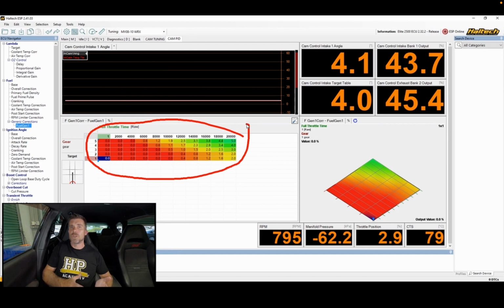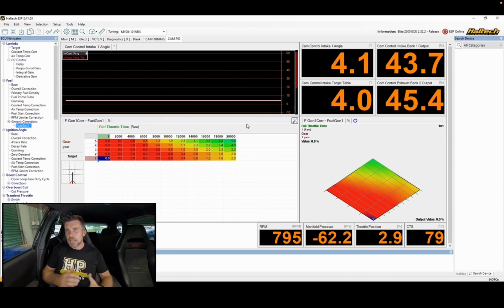Whether you want to do this with just the fuel or the fuel and ignition is completely up to the individual. As I've mentioned, it's a slightly clunky workaround that we've got here with the Haltech. Most ECUs will give us the ability to just switch wholly between 2 fuel and 2 ignition maps. It's important to make sure that we are using the output for our switch cam control to actually function between those 2 maps. It's going to make sure that we're always on the relevant map for our particular application.